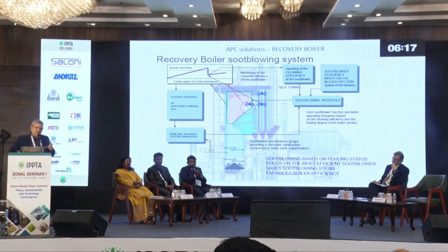Soot blowing is one of the key aspects. People may say, why do you put soot blowing as separate? Because the boiler generates HP steam and you are using the HP steam. I want to utilize it in a very organized, optimized way. So that is called smart soot blowing.